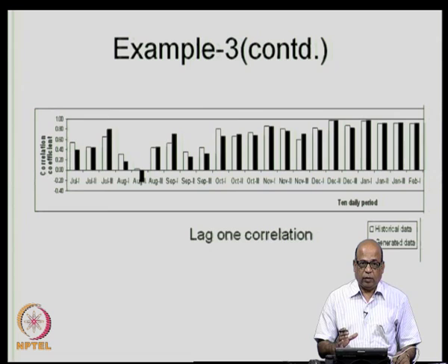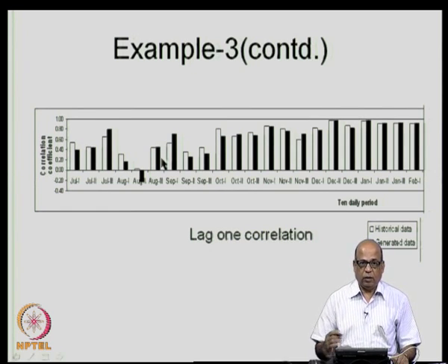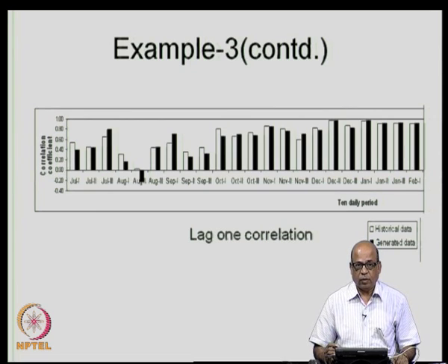So, this type of generation we use in applications such as reservoir operation. What we exactly did in this particular case is that the flows into Sardar Sarovar reservoir from the historical available data, let us say we had 40 years of data at the reservoir, 10-day periods. We generate this for let us say 100 years, 200 years, etc. Several such sequences. How do we generate several such sequences? By using different sequences of the random numbers that appear in the model. By generating different sequences of random numbers, we generate different sequences of flows. Like this, let us say you have several sequences of 50-year data, 10-day period data.